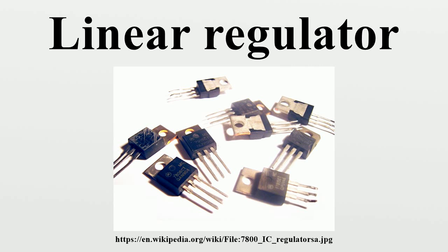Adjusting fixed regulators. By adding another circuit element to a fixed voltage IC regulator, it is possible to adjust the output voltage. Two example methods are: a Zener diode or resistor may be added between the IC's ground terminal and ground. Resistors are acceptable where ground current is constant, but are ill-suited to regulators with varying ground current.